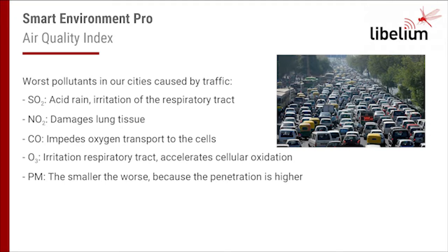What is the air quality index? The worst pollutants in our cities caused by traffic are SO2, NO2, CO, O3, and the particle matter. The particle matter is especially dangerous. The smaller, the worse, because the penetration is higher. And the other gases are the cause of acid rain, damage in the lung tissue, impede the oxygen transport to the cells, or cause irritation in the respiratory tract and accelerate the cellular oxidation.